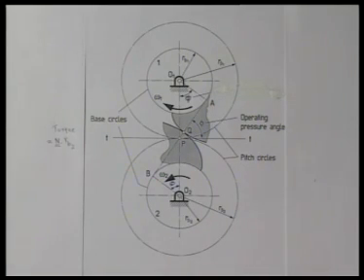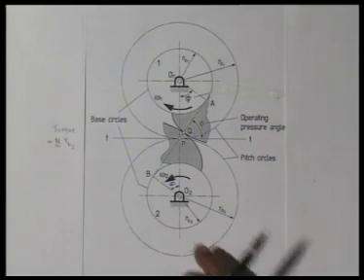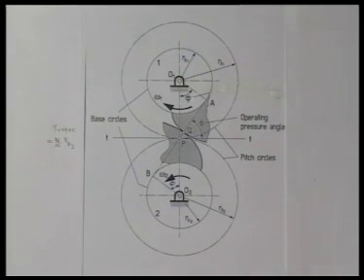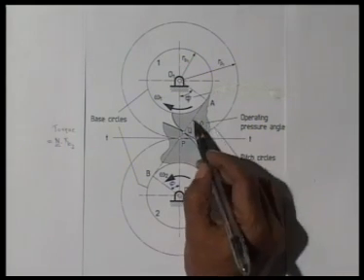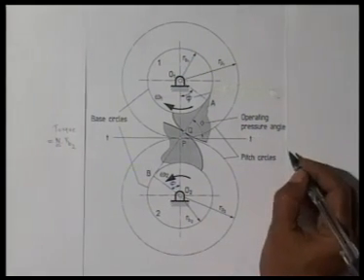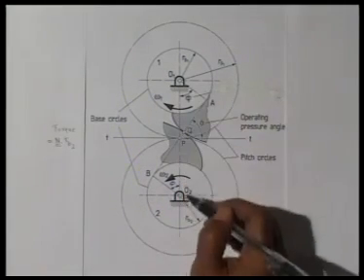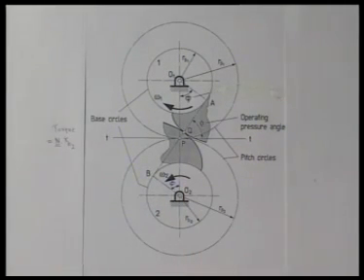This enhances the life of the bearings which are used to mount these two shafts on the foundation. Thus the pressure angle remaining constant implies that under steady torque the bearing reactions are not dynamic, they are static. That is the advantage of pressure angle remaining constant.